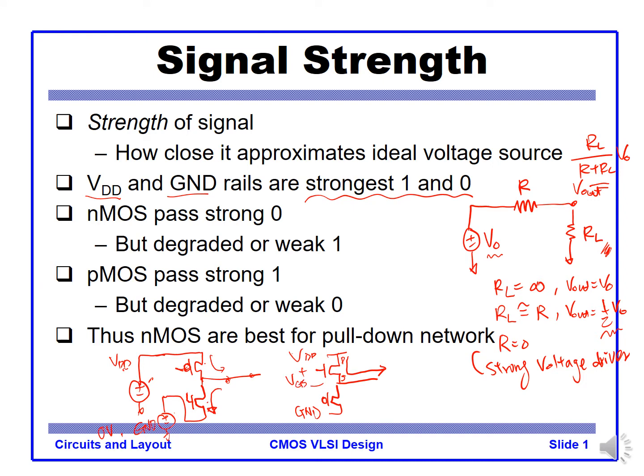We always care about VGS here. For the given current direction, the transistor is on only if VGS is greater than VTH. Once VGS gets close to VTH, it will be turned off. So the maximum pull-up VO max is limited to VDD minus VTH.